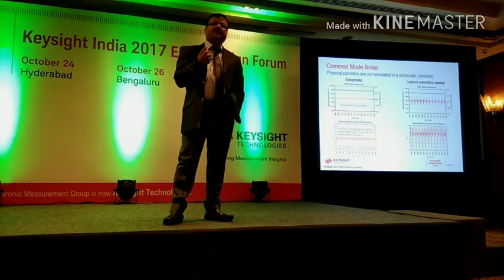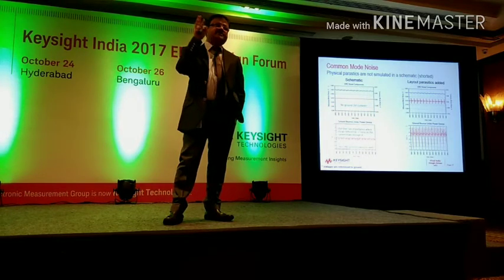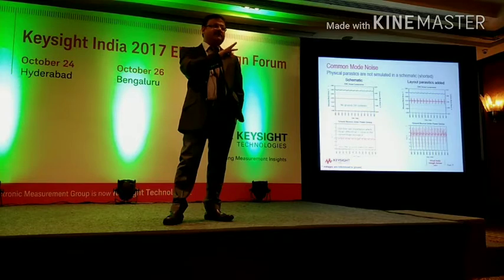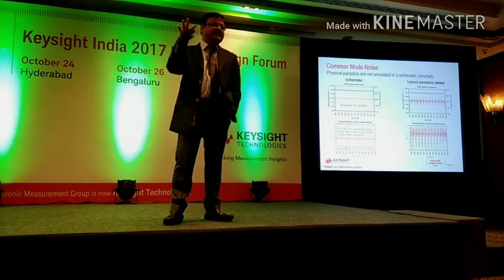So power electronics is probably going through the same phase which high-speed digital guys went through maybe 10-15 years ago, when people suddenly woke up and realized, I can't do the layout the same way I was doing it for a 50 Mbps or 100 Mbps kind of data line. Now I'm routing 2.5 Gbps, 5 Gbps, 10 Gbps.